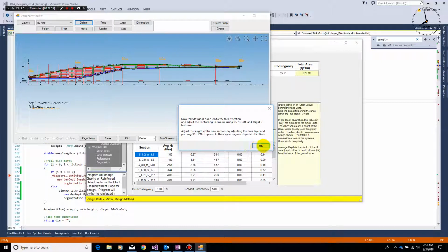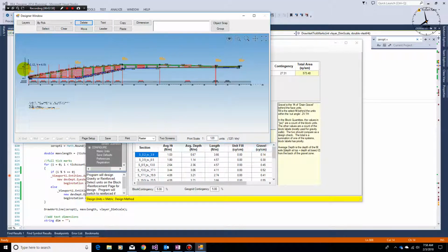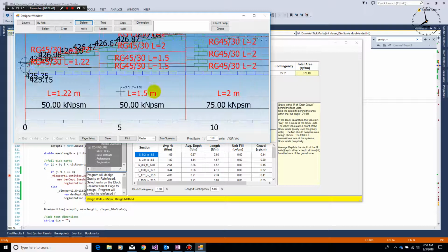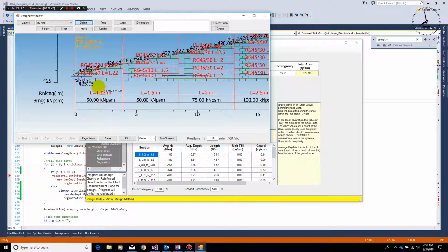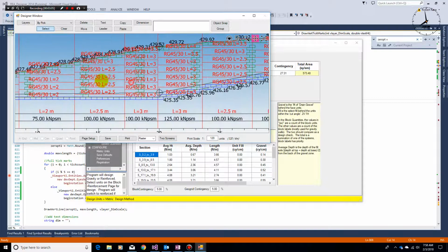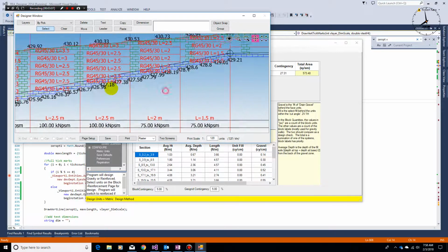And there we go. So this is a new elevation. We can zoom in on it. A lot of noise here because we're showing a lot of stuff, but I label every, let's just get rid of some stuff here. So I label every step in the wall. So we've got a top of wall, bottom of wall. So when the contractor goes to lay it out, we can see that, hey, these are what the elevations should be, and you can see where we're stepping up here.